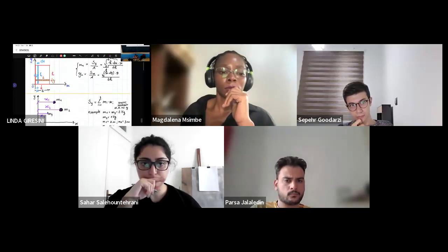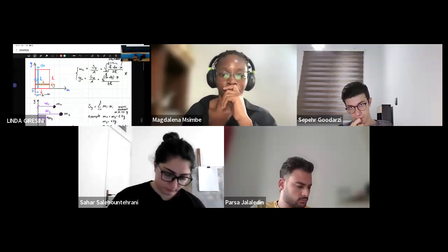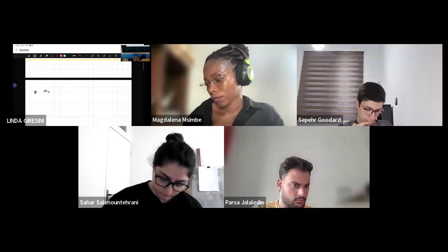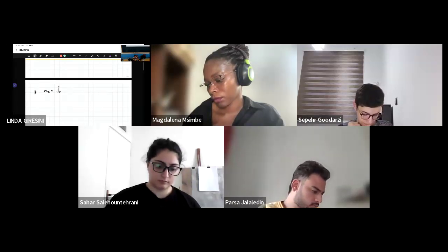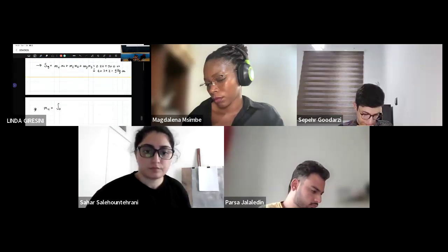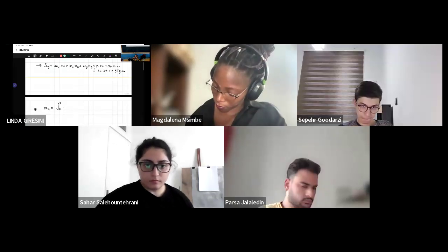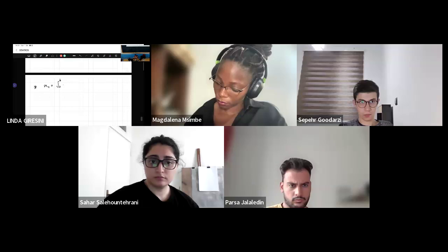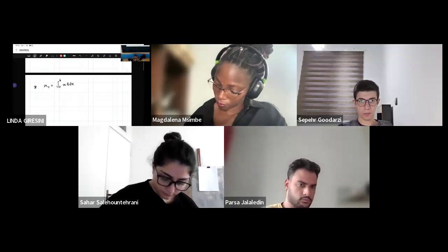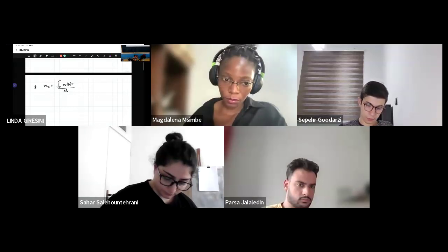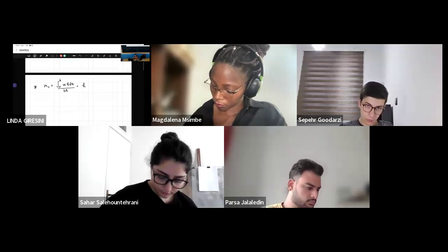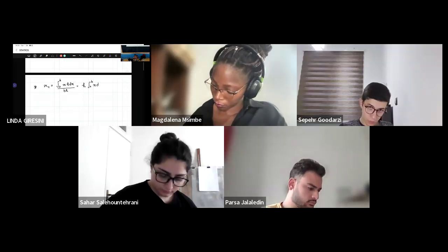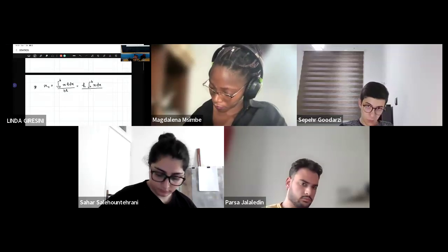So now we continue. Now we take these equations. We move them here. Xc is equal to, we said, integral from 0 to b. Now it's better to put always dx at the end of the integral. So we have xh dx divided by bh. Now h is constant, so it can be put out of the integral from 0 to b of x dx, and everything divided by bh.